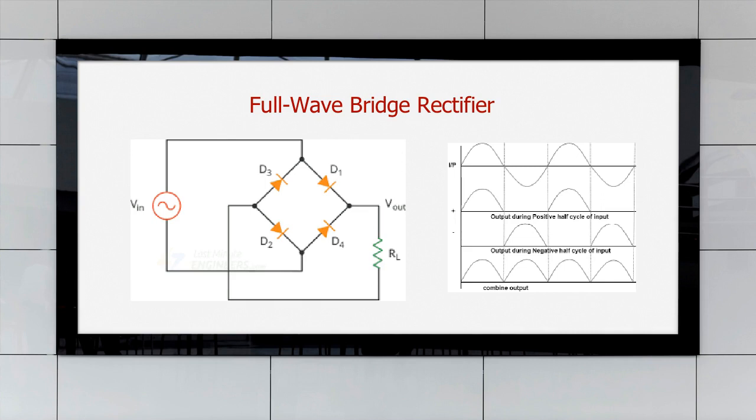This is ground because all these wires are grounded. Now with ground and +5, ultimately the voltage across this D3 is -5 volt from plus to minus. So this is reverse bias, so the current will flow in this direction. It will follow this path: D1, RL and again D2, and complete the circuit.